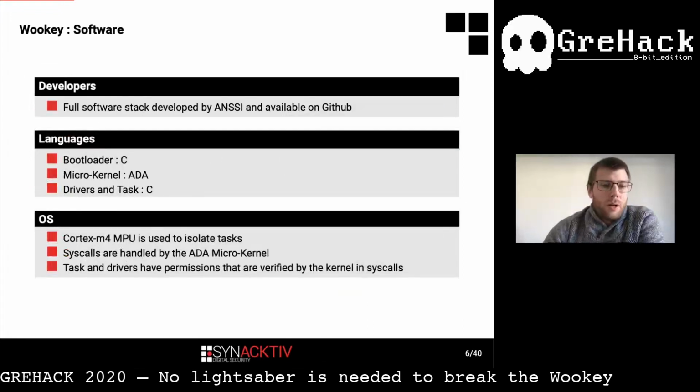For the software, all the software components are developed by the agency. The bootloader initializes the hardware, performs security checks, and loads the operating system. It's written in C code. The microkernel, which is called Ewok, is coded in ADA. It implements syscalls for hardware usage, IPC communications, and task scheduling. Developers chose ADA to build a safer and more secure kernel.